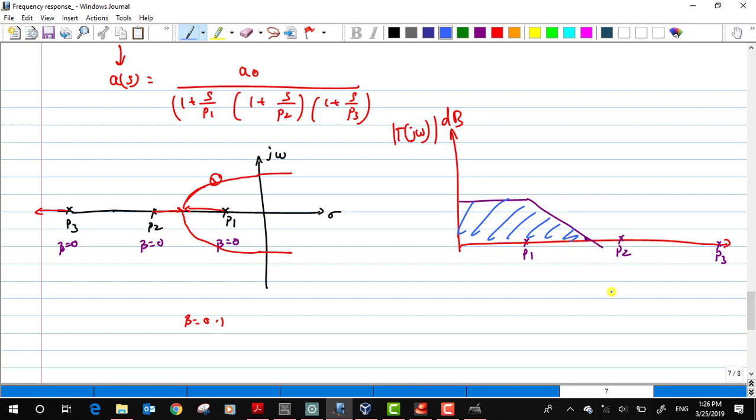Now for this case, this line acts as 0 dB. As far as the loop gain is concerned, this particular line is the 0 dB line, and the magnitude is pretty simple: you subtract both these things, or you write it as 20 log of T naught, and that is the height of this magnitude plot. Now how do I plot the phase? What happens to the phase? And how do I relate it to my Bode criteria here?